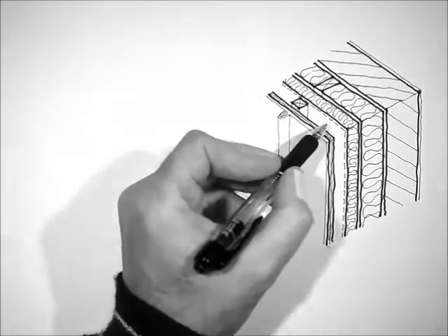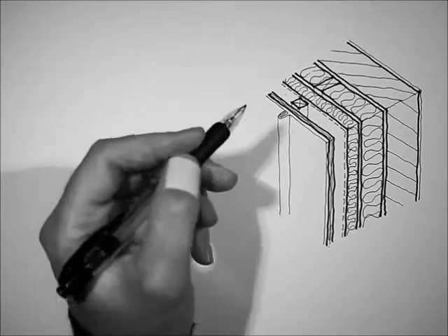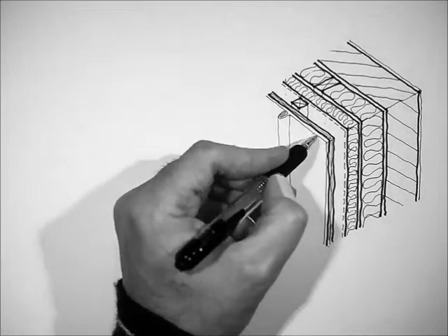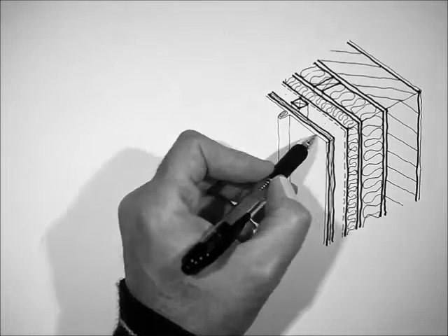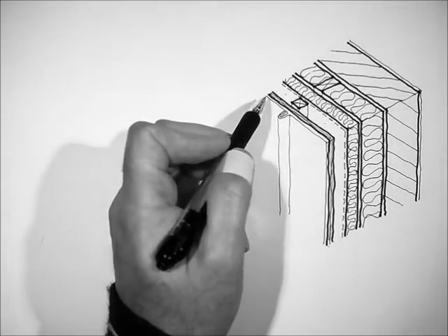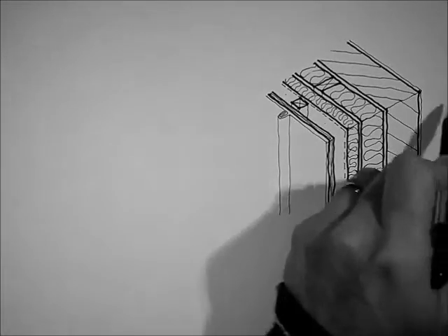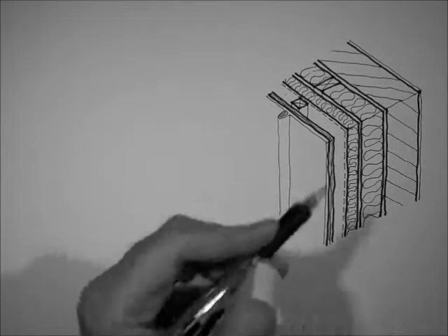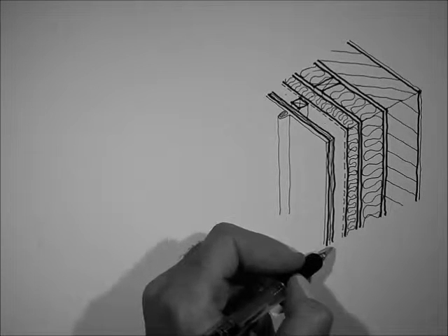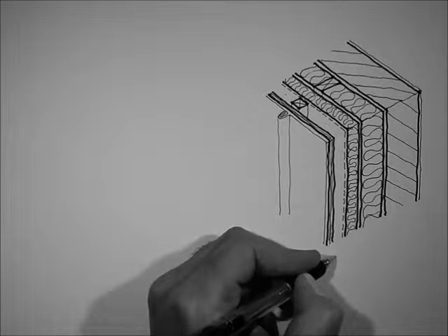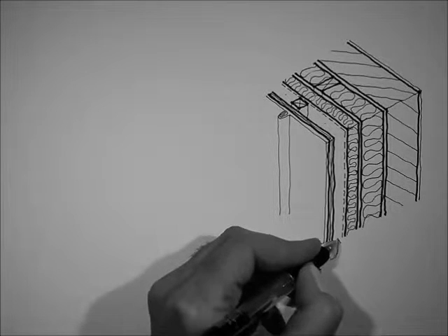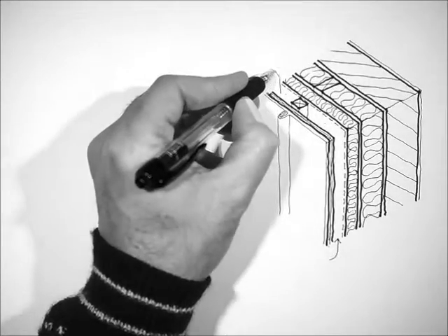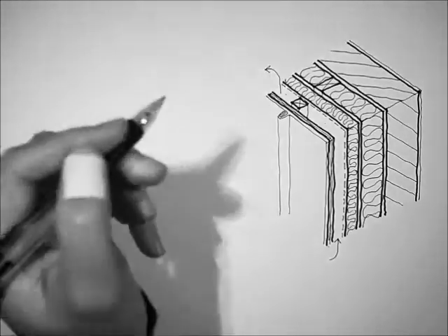Now the reason I'm saying there is a gap in here is because the zinc closes the external envelope of the building and prevents the vapour from getting away, the vapour from us living in buildings, breathing, making coffee, having showers. So at the bottom of the wall there needs to be a ventilation route into that cavity, and at the top of the wall there needs to be a ventilation route out.